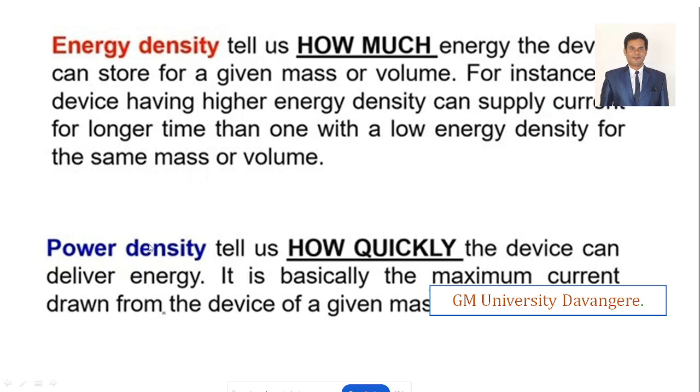We use capacitor banks, especially in power grids, to switch the reactive power into the transmission lines, because most of the devices are inductive loads. When you talk about inductive loads, reactive power matters a lot.